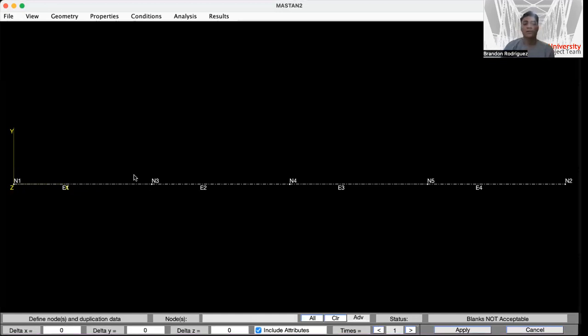Let's start building at another height, because we want to make a truss, right? So let's select these 3 nodes, 3, 4, and 5, and let's duplicate them 36 inches upwards, because we want that top horizontal chord of our truss. So I selected them, delta Y.